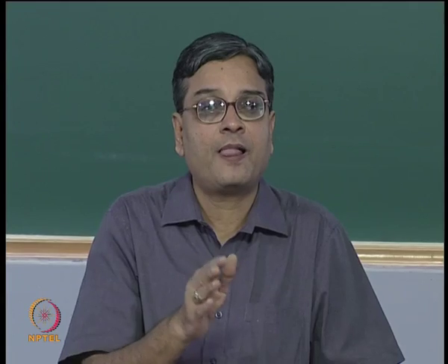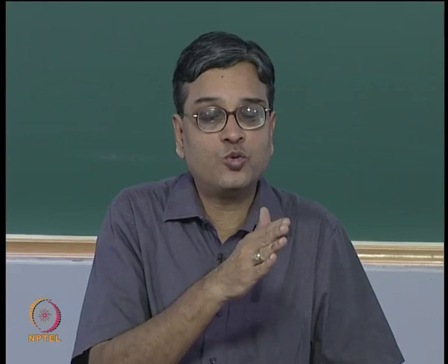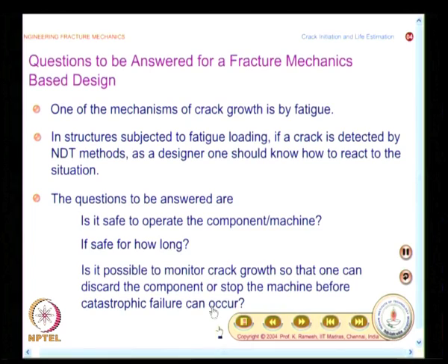Every takeoff and landing, you will have engineers to come and inspect certain aspects of the aircraft, and after so many hours of flying they have a schedule what components have to be looked at. So, you have a schedule developed. If you have to develop a schedule which is also going to give you safety for the passengers as well as the structure, you have to have a scientific basis and decide these schedules.